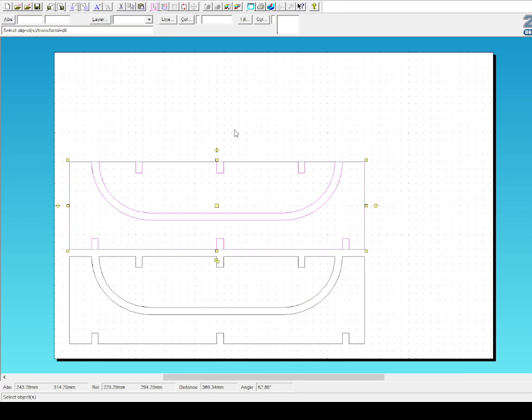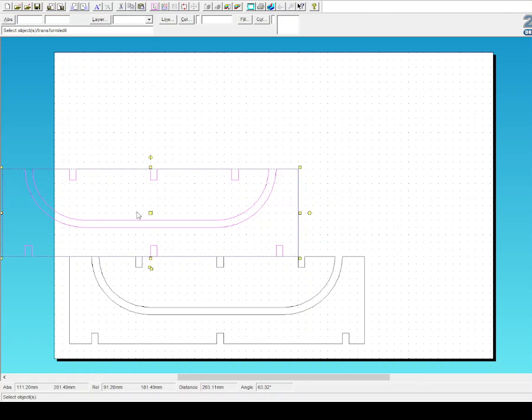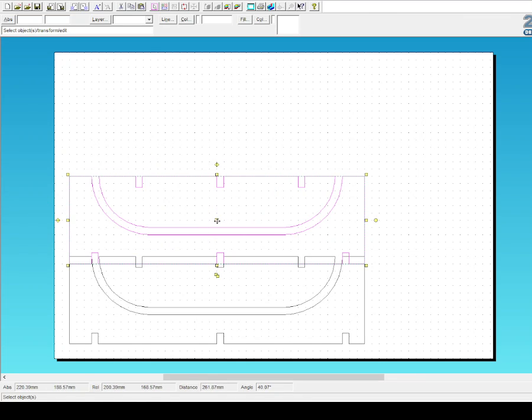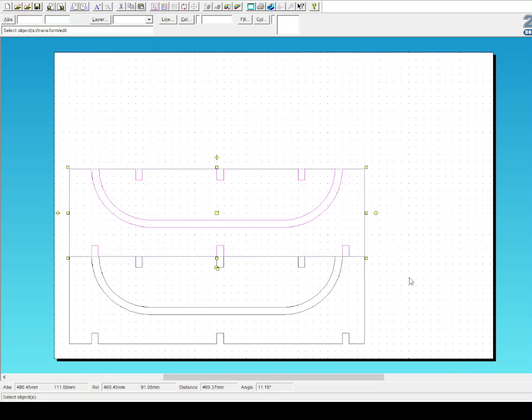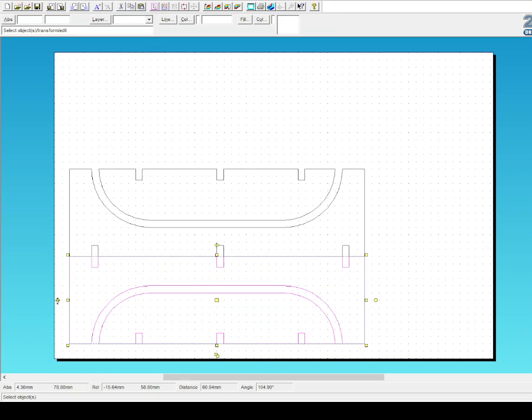I'm going to copy it again and paste it again with gridlock, because then it will snap to the grid. If you want to be conserving of your materials, you want to have that snap together. Oh, not like that, just up one. Perfect. Okay, and you can see some of them are slightly random, that's okay. In theory, you could flip this bottom one, if you wanted to match up the things, so that the laser cutter makes less paths, less runs if you like. It looks nice and symmetrical.